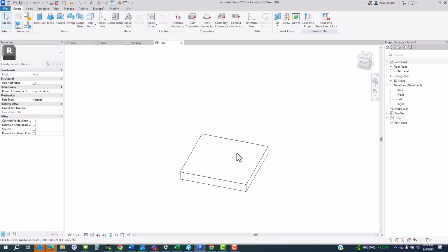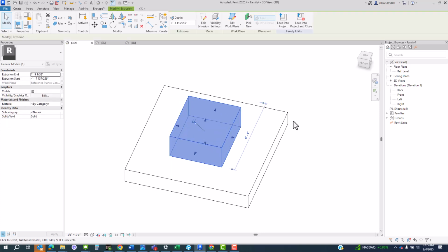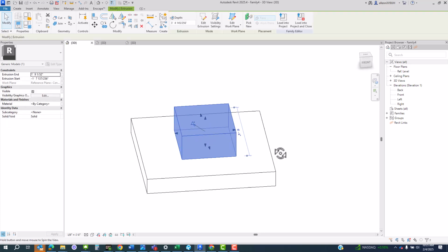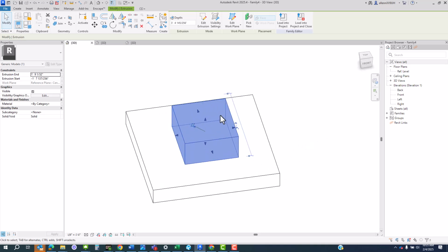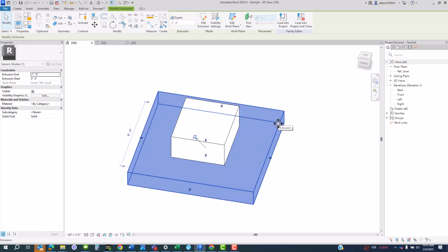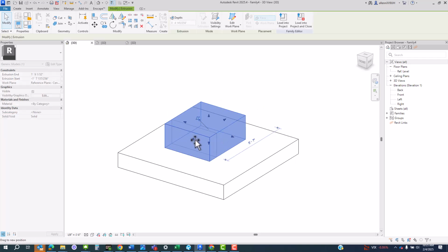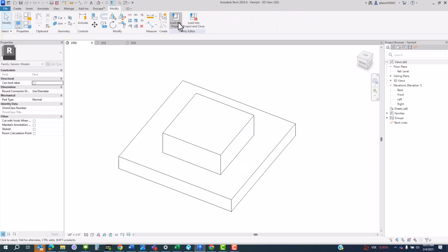And after you've created it, it will show up in your next project on whatever you want to be the active host. Take, for example, a simple box like this. This box is attached to the host, and the back of the box will continue to be the back of this object when I load it into my next project. And instead of being attached to this host, it'll attach itself to any surface that I can find within my project. This shape is still very fluid, so I can change it, do whatever I want, and then when I'm ready, I'll load it into my project.